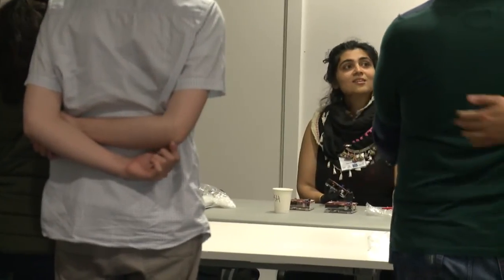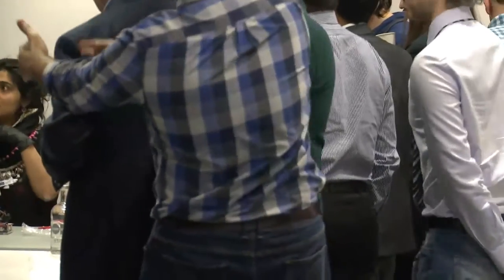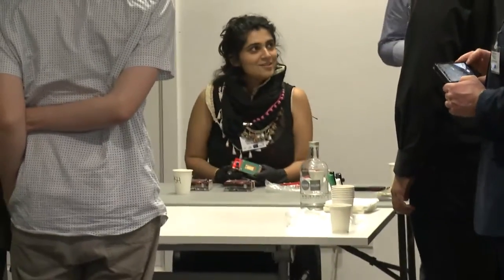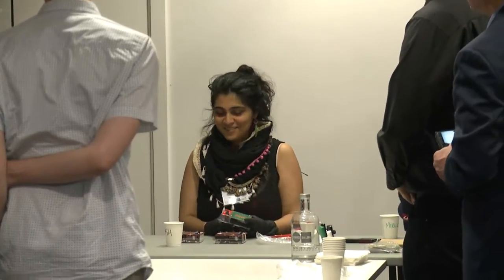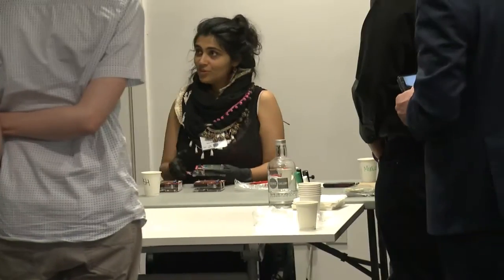Some of them need baking as well, so you mix Teflon, for example, with Parylene C. Teflon is the insulator and dielectric, Parylene C is the dielectric, and you have a certain mix. You spin coat, and then you bake for 8 hours, and then it runs for like 3 minutes before it gets contaminated from the dust in the room. So we're thinking, okay, what can we have that is cheap, doable at home?